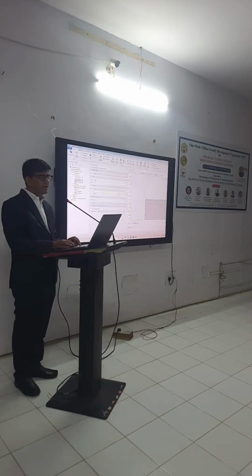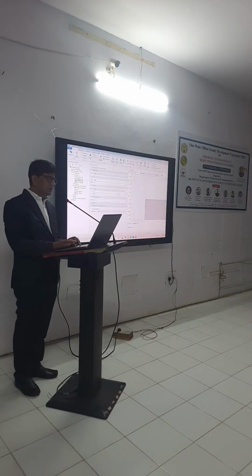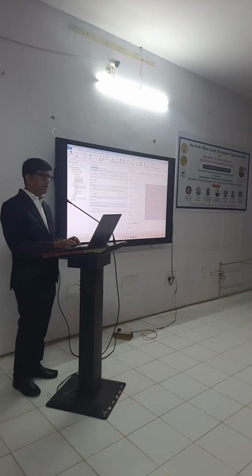And what is my height again? Instead of 100, now my height is 100.15, because height of your substrate plus height of your bottom electrode. So 100 plus 0.15, and I will click on build selected. So I created my piezoelectric layer.